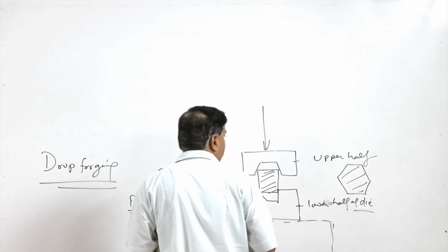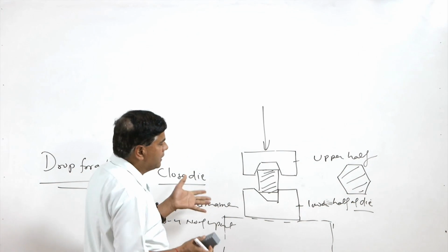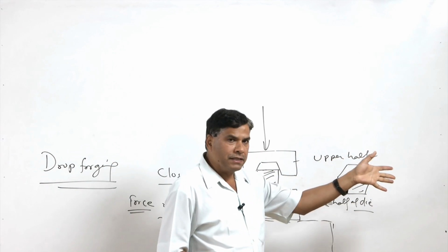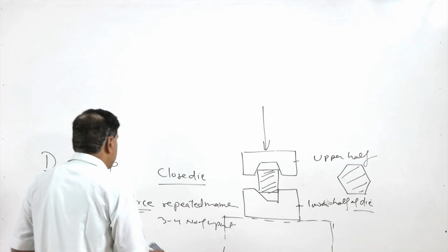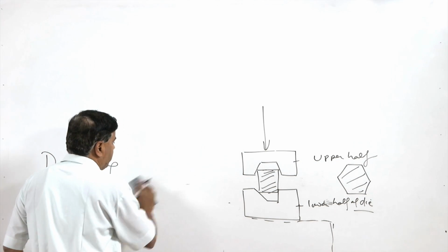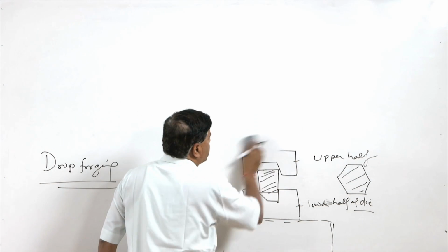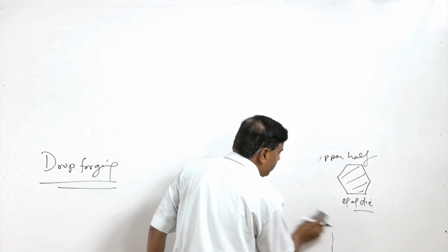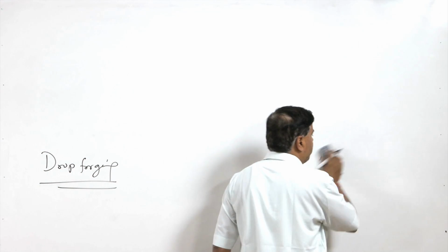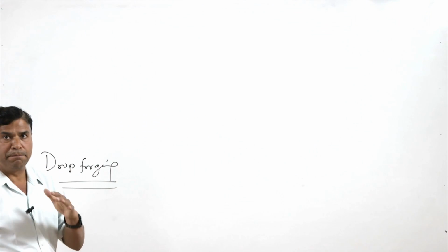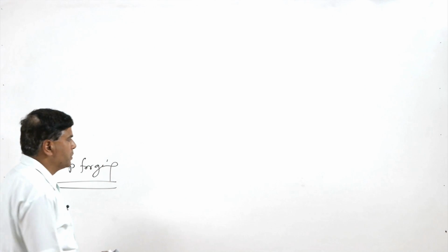This may not be the final product. So, in order to get the final product, we may have to make a number of dies with the gradual change in the shape. So, for that purpose, a systematic procedure of shaping using the forging die is used, since it uses a number of impacts in the drop forging.